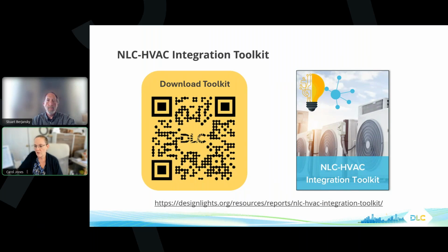We have two-way communication. We can connect to the other digital systems and talk to each other and say, hey, how can I help you? That's different, and there are a lot of opportunities out there. So HVAC and more. Yeah, and in large buildings, you tend to do this with BACnet, and the integration wasn't happening as much in small to medium-sized buildings. That's starting to happen more now because of thermostats.